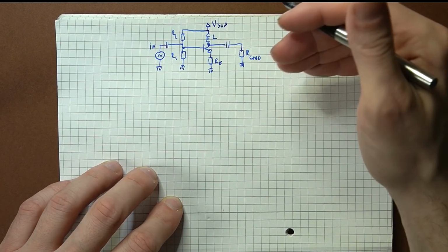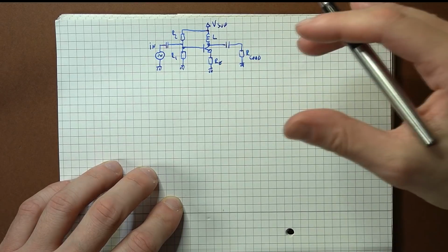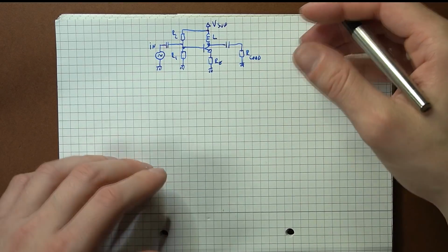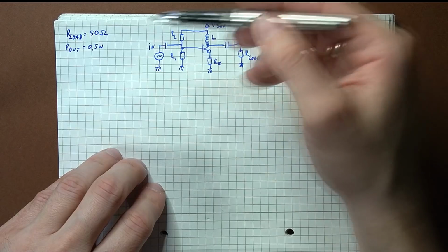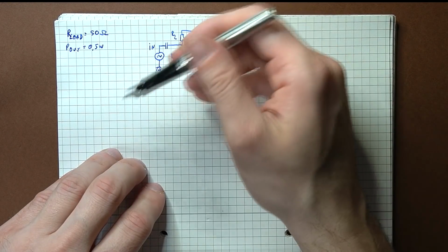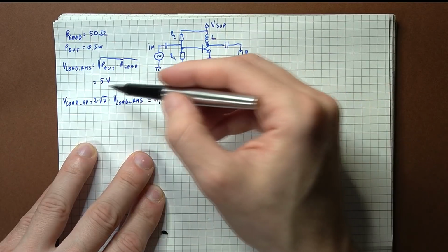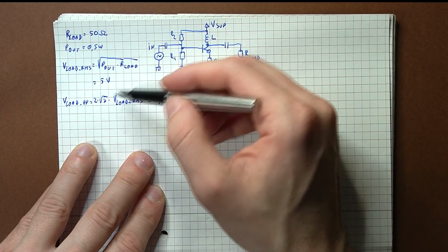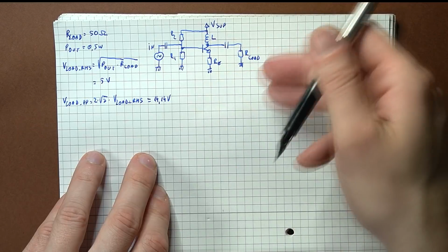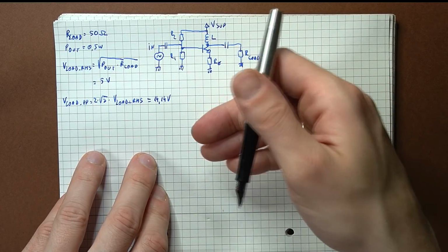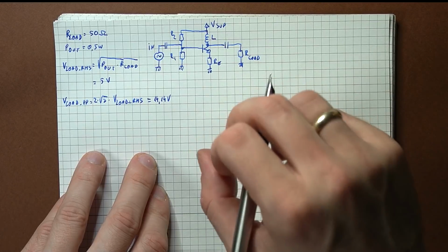Now, I won't be using any impedance matching, first of all to keep things simple, but also to get a wide bandwidth frequency response. So to start calculating the components, let's start with what we actually know. Knowing the output load value and the output power, we can work out the output voltage that we need. So we will need a 5 volt RMS voltage, which translates to a 14.14 volt peak-to-peak voltage. Now, even though this configuration can supply double the supply voltage on the output, we will need a bit more than 7 volts to supply the circuit.